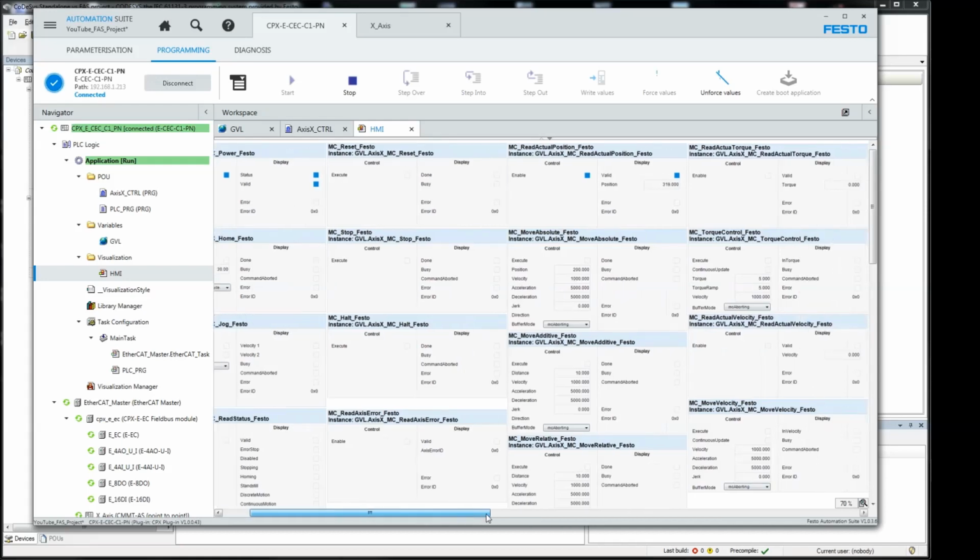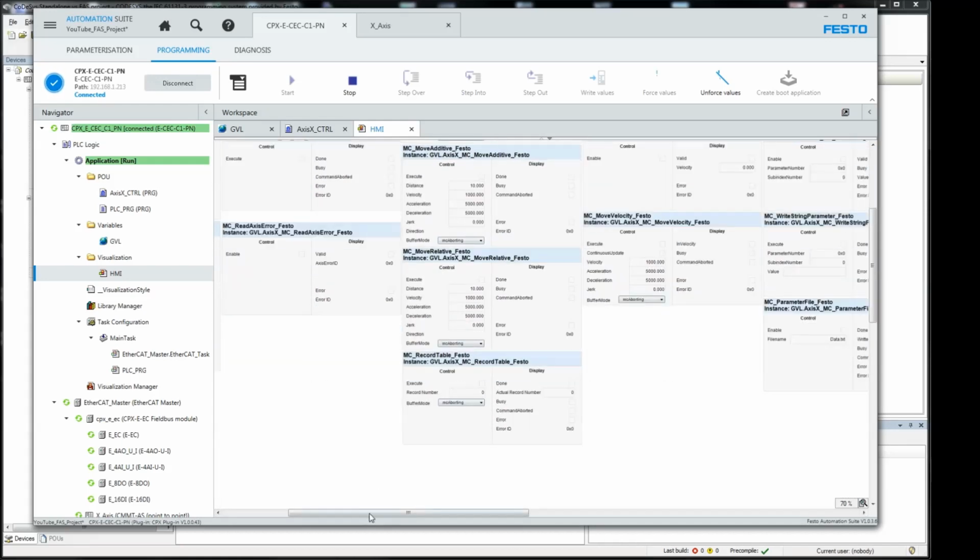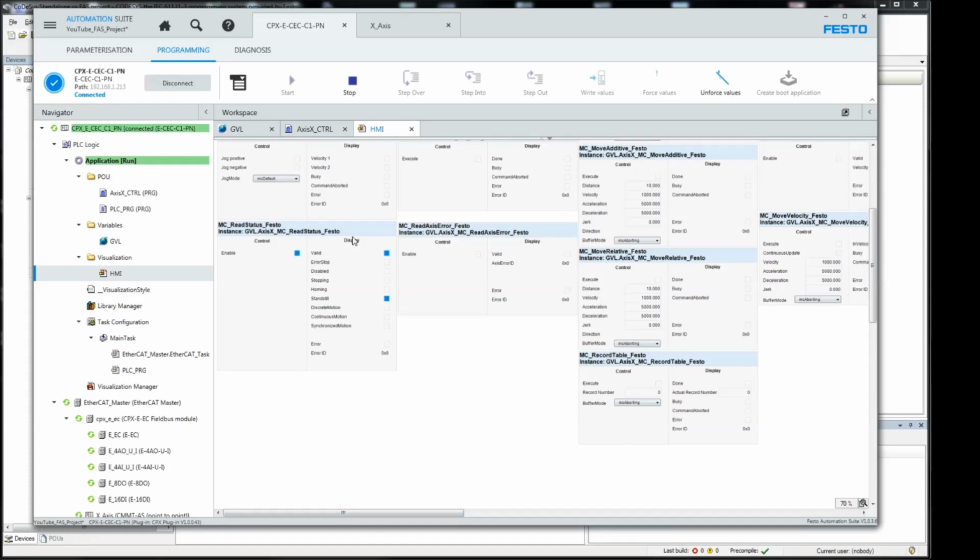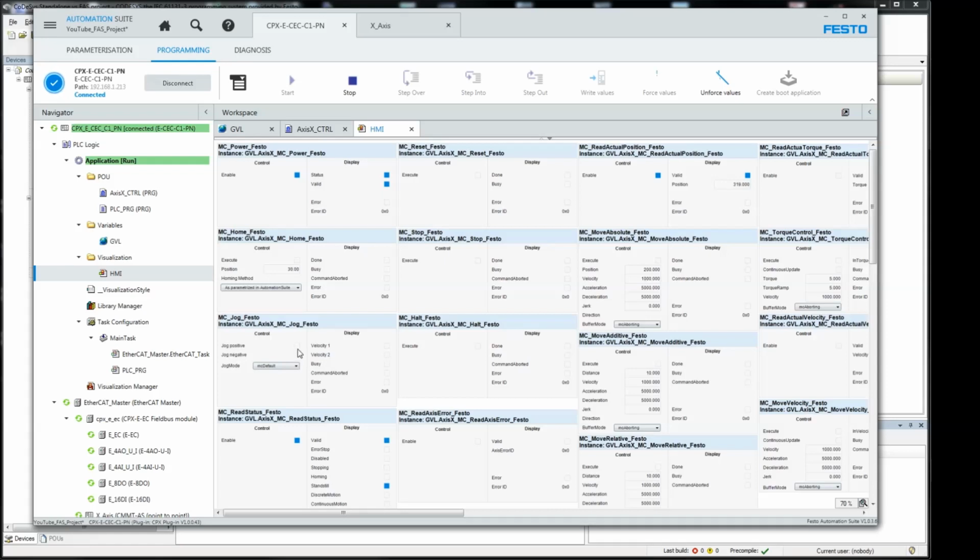I can, there's some status stuff here. This right here, I can read status right here. I can jog the axis. It moved forward to 350. And I could jog it back. Where's the jog again? You see it changing over here? And basically you start playing with the drive. I mean, I can home the axis, put a 0 in here, home the axis. It's now moving to its home position. You see the axis is changing right here.